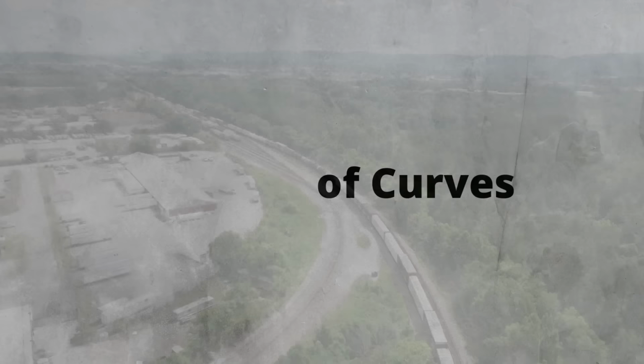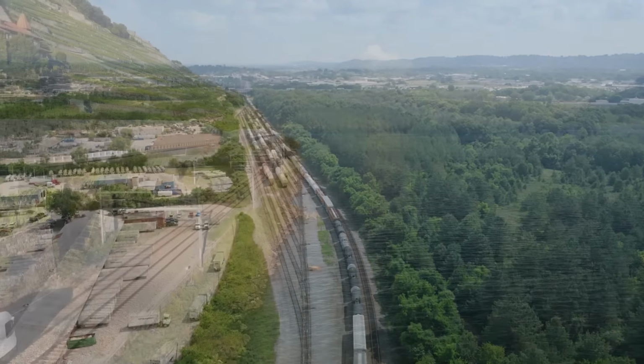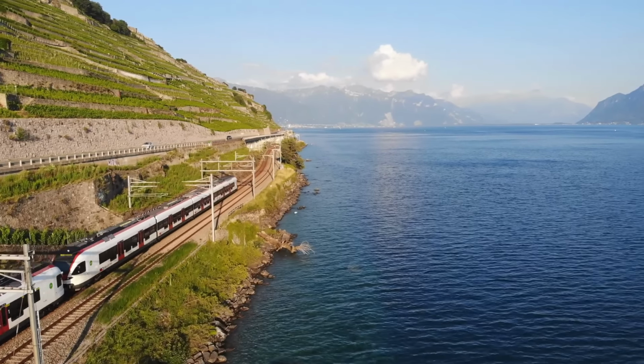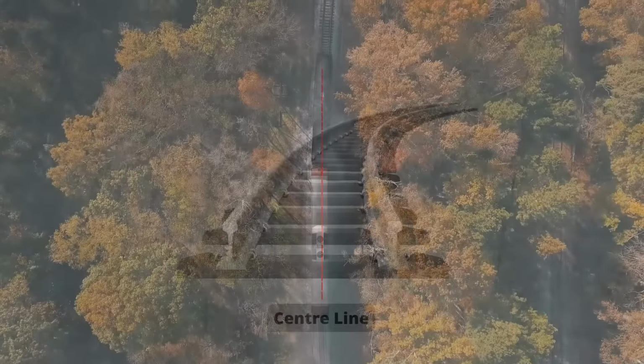Before we dive further into curves, it is worth taking a minute to understand what is meant by the handing of a curve. This is a term that you may hear often, and for your understanding it's good to know from the start. The handing of a curve is simply a way of describing the direction it deviates from the straight. For example, a right-hand curve moves away to the right-hand side of the centerline.